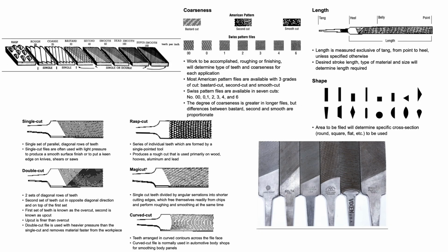Curve file, it is also known as Vixen file. The curve file cut is used for filing of the wide surface of soft metal like aluminum, zinc, copper, and brass. It has circular teeth. And spiral file, whose cut is round and semi round files.